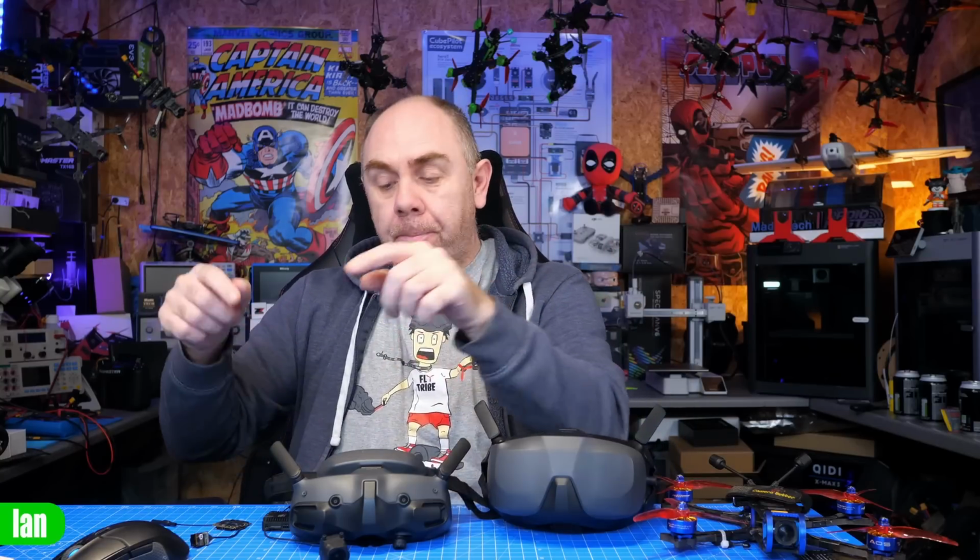So to start, DJI have introduced a new race mode with O4. This new race mode is not available on the O3 air units. It is not available on any of the other DJI systems. It is only on the O4 Pro and the O4 Lite air unit. This new mode is also only compatible with the latest DJI goggles, which is the DJI Goggles 3 and the DJI Goggles N3. Whilst you can use both O4 air units on the Goggles 2 and Integra, the Goggles 2 and Integra do not support race mode. It is only the new goggles that support race mode.